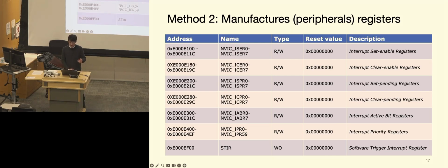And for direct register access, you have more control over specific hardware features and it's potentially faster to execute because it saves a couple of clock cycles. The disadvantage, as you can probably imagine, is that it's not as compatible with other devices if you want to work with different microcontrollers. Also, it requires deeper understanding. You have to know what you're doing.